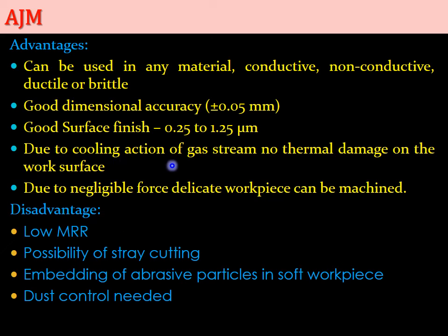Due to the cooling action of the gas stream, there is no thermal damage. This cooling is the major role of the gas stream. These gas streams are used as coolants in this process, so there is no thermal damage on the work surface. Due to negligible force, delicate workpieces can be easily machined. But this process has other disadvantages: low MRR, possibility of stray cuttings,